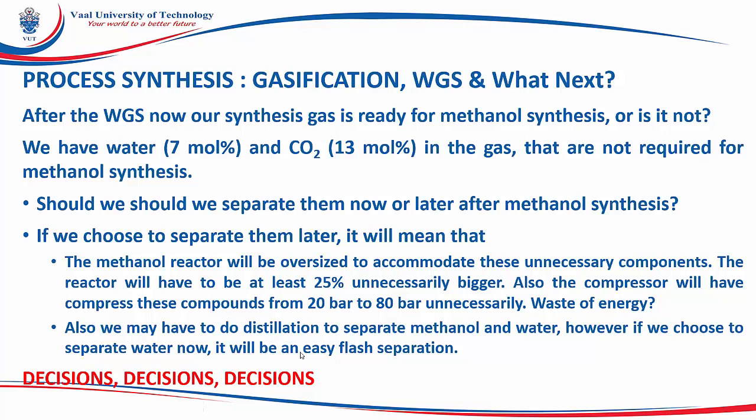I need to remove the water. Separation of these gases and water will just be cooling down to a lower temperature where water will condense, and then I'll separate the water. And then what do I do with the CO2? Do I let it go through the methanol synthesis reactor, or do I separate it right now?